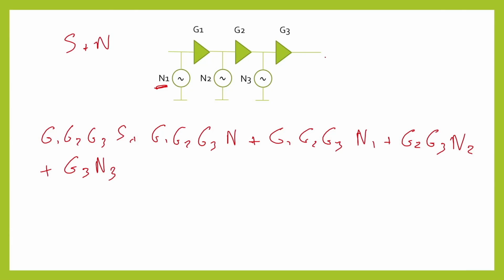So it's important that we prioritise noise as early on in the circuit as possible, because once we've got noise into our signal, we can't remove it whilst keeping the bandwidth the same. There are clever digital signal processing techniques you can do based on knowledge of the signal, but from an analog perspective, once we've degraded that SNR, we can't do anything about it.